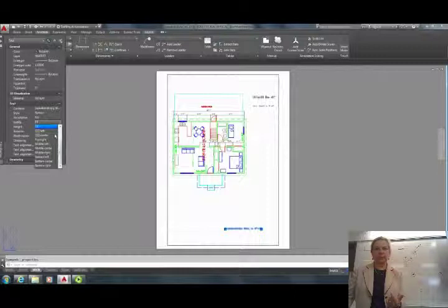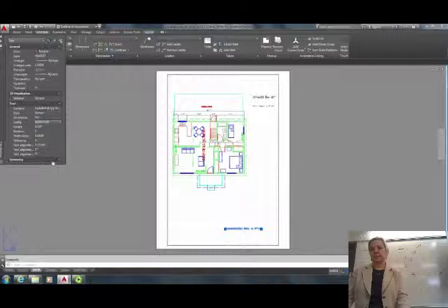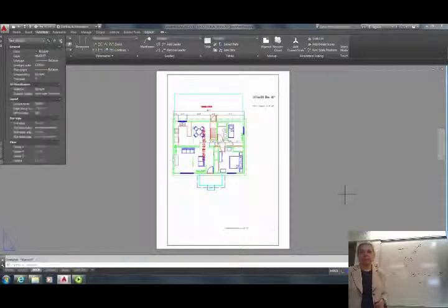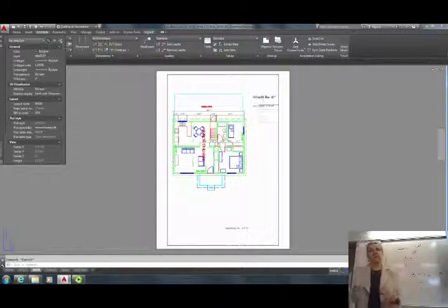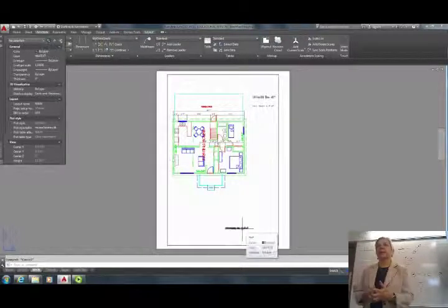Top left. Top bottom left, I think is the standard, isn't it? Okay, so you see this height is in model space, this height is in paper space. They will both come up the same, and I'm controlling the height by knowing what I want and knowing whether I'm in paper space or model space.